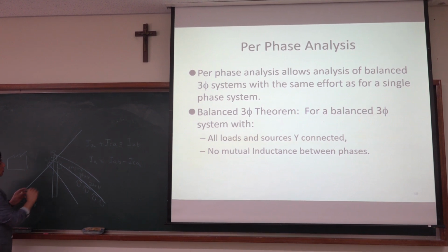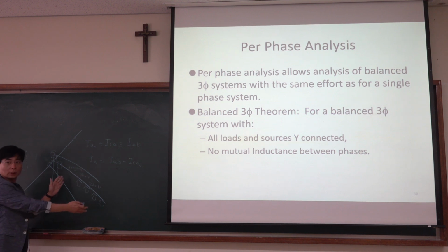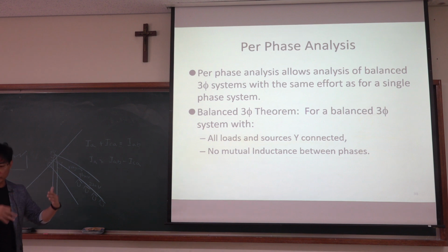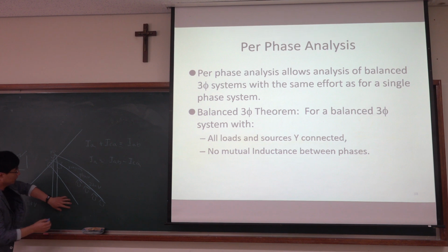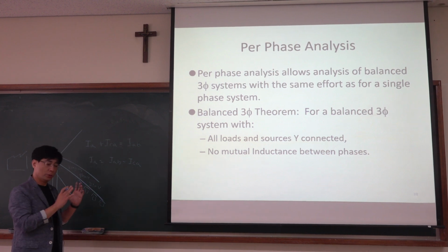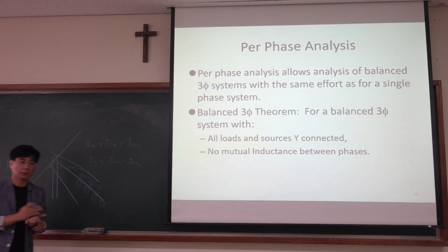Anyway, so we have 3 phase, but in this case, it is not easy to balance these 3 lines. The reason is because we only have a small number of loads. And maybe the number of households is different. And even if they are the same, the random behavior of the load consumption makes the power consumption here and there different. So typically in a distribution network, we need to use unbalanced 3-phase analysis.